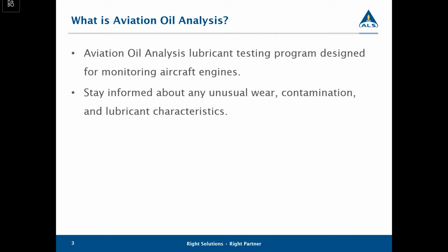It helps you stay informed about any unusual wear, contamination, and lubricant characteristics. Those are the main three focuses when we're doing the analysis. We want to make sure that there's no abnormal wear. We want to make sure that there are no outside contaminants coming into the system. And we also want to make sure that the lubricant itself is meeting the specifications for what should be in that system.